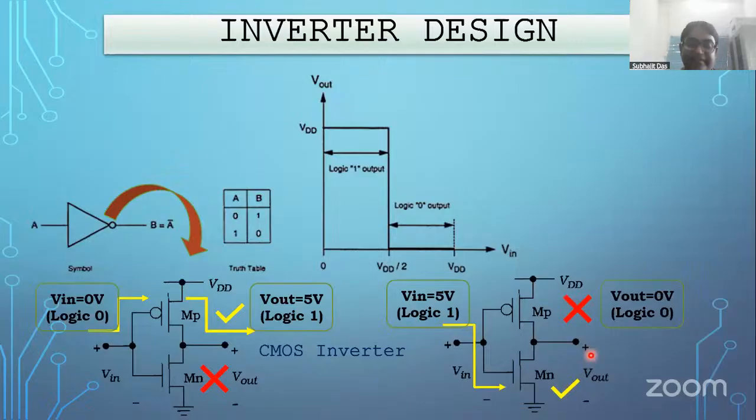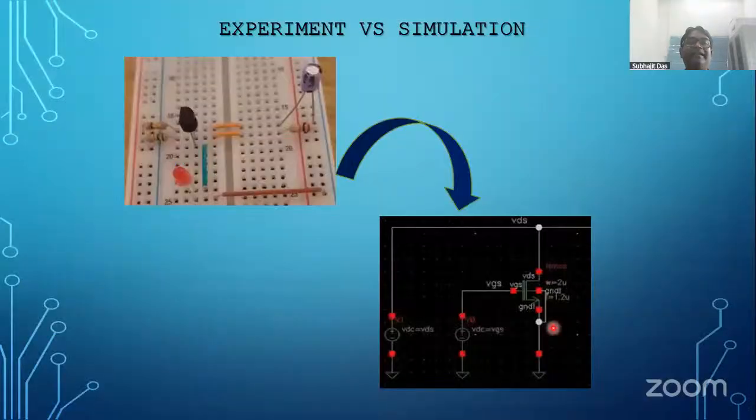This is basically the inverter. This is the corresponding circuit. We learned that, but we want to design that inverter. I told you that with Cadence we can do full custom design, meaning I can design each individual MOSFET. I can change the dimensions of the individual MOSFET, and we can see how fast it will be. Now I will talk about the difference between the experimental and simulation.